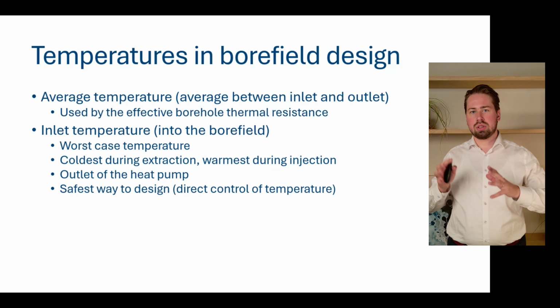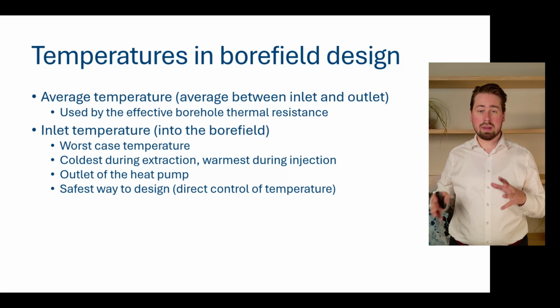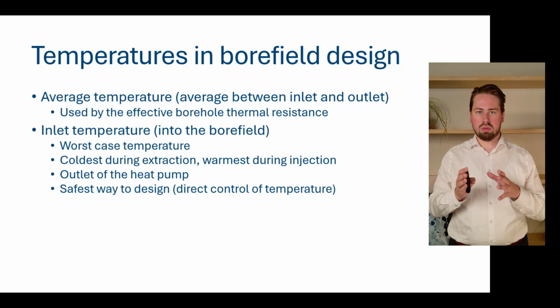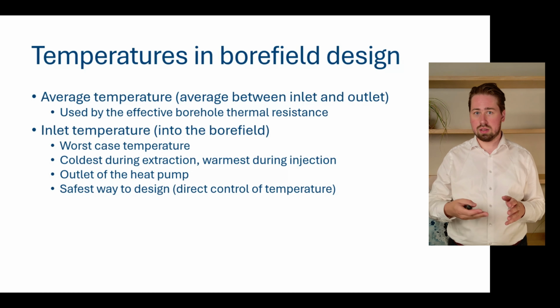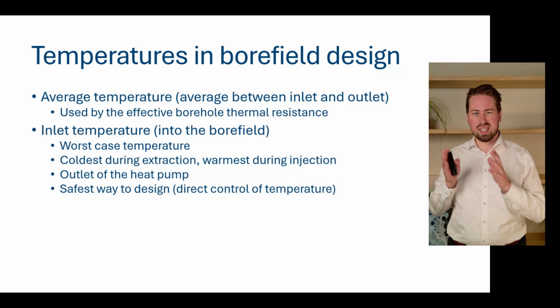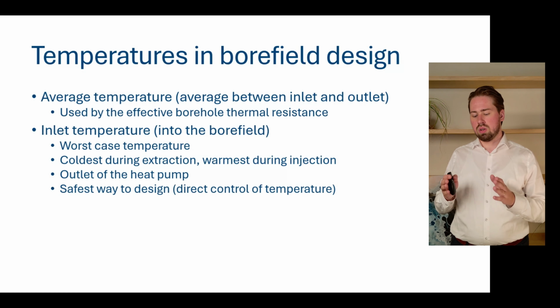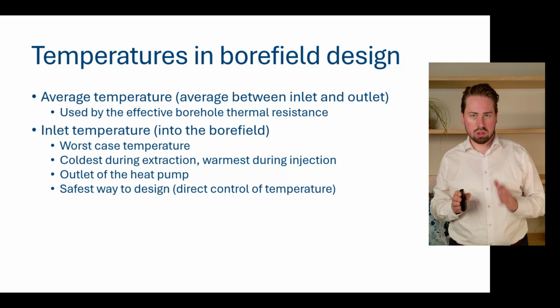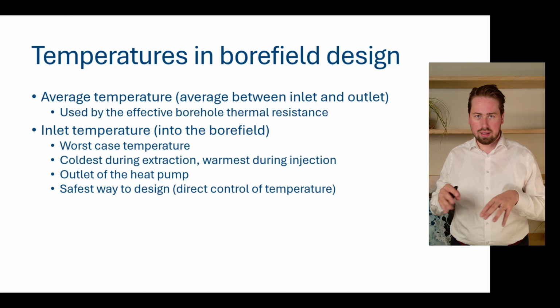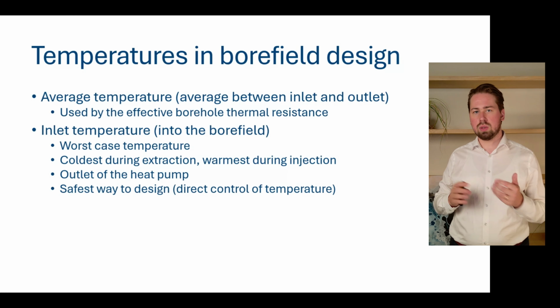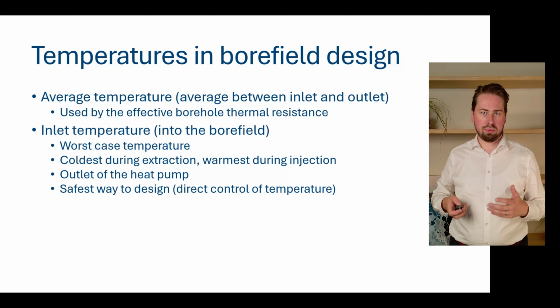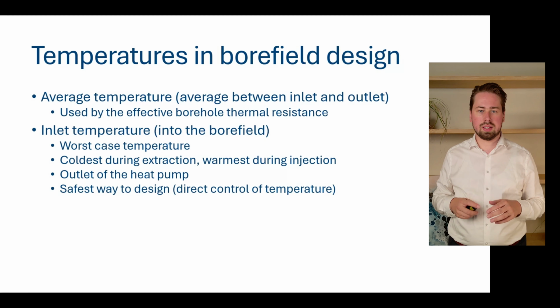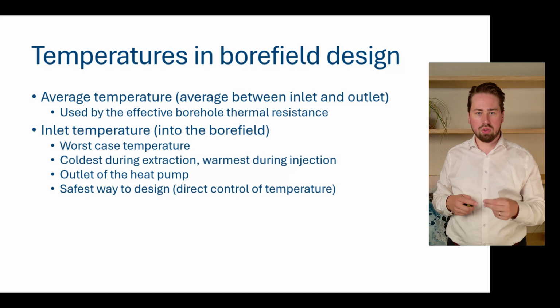So the inlet temperatures are the absolute minimum and maximum temperatures, and if we want to put limits in place, like there is some regulation in specific countries, especially on this inlet temperature, we know that if we say between 0 and 25, there is no fluid anywhere inside our bore field that will be below 0 or above 25. So it's the best or the safest way to design, because you directly control the temperature.